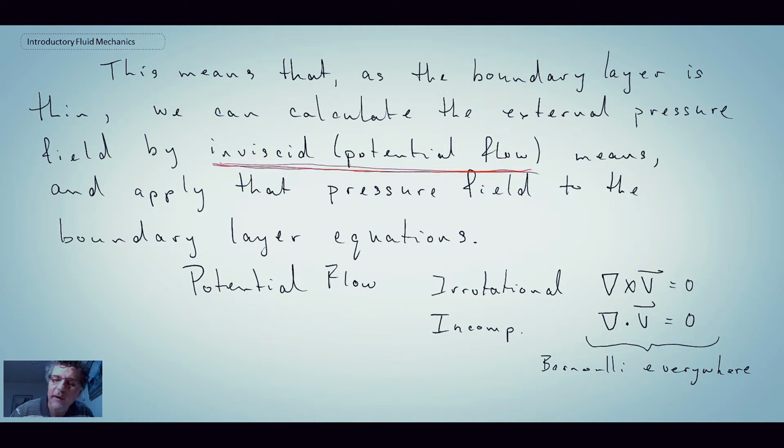And with that, we're going to use that for the boundary layer analysis. And specifically, we're going to use it to address the dp by dx term. We already saw that dp by dy was approximately equal to 0. There's no pressure gradient normal to the wall, but we still need to deal with the dp by dx term. And for that, we will use Bernoulli's equation.